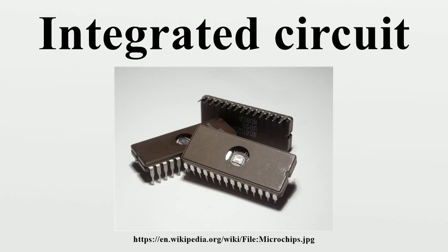The name is taken from the term very large-scale integration, the current state of the art when WSI was being developed. A system on a chip is an integrated circuit in which all the components needed for a computer or other system are included on a single chip. The design of such a device can be complex and costly, and building disparate components on a single piece of silicon may compromise the efficiency of some elements. However, these drawbacks are offset by lower manufacturing and assembly costs and by a greatly reduced power budget. Because signals among the components are kept on die, much less power is required.